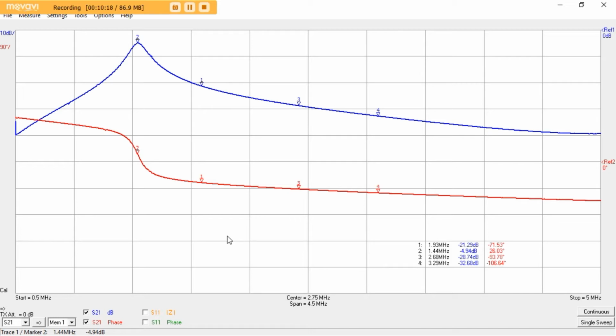We've basically put a 50 ohm impedance on the top of that coil. The input terminal on the network analyzer is nominally 50 ohms across the frequency range that we're working in, and that has loaded the secondary coil, reducing its resonant frequency.